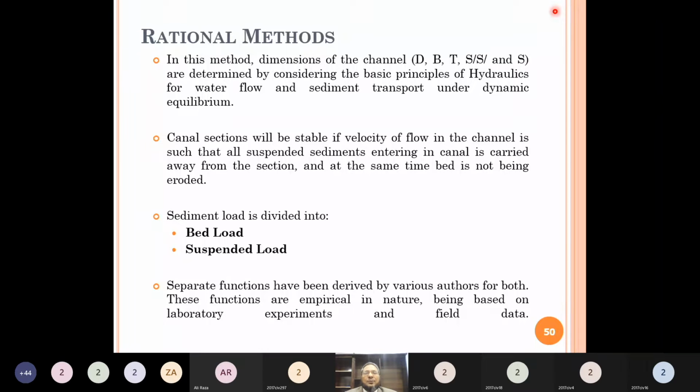Number 2, what would be the bottom width of the channel? Usually irrigation channels, they are of what shape? कौन सी shape होती है? Rectangular, sir. Trapezoidal channels. Irrigation channels, government owned irrigation channels, they are usually trapezoidal in cross section. Water course is rectangular in cross section.